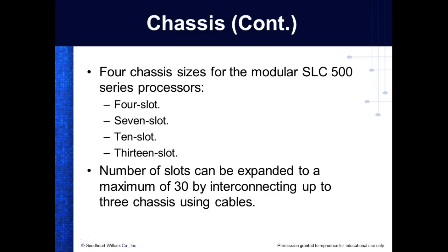So we have these come in different sizes for the 504. You can buy it at a 4-slot rack. You can buy it with a 7-slot rack, which is what we got. A 10-slot rack or a 13-slot. We can use extenders or expand it up to a maximum of 30 slots for the 500 series. Okay. So every PLC's got a limit on the number of modules you can hook up to it, because that's the addressing capabilities when it goes out and addresses these modules.